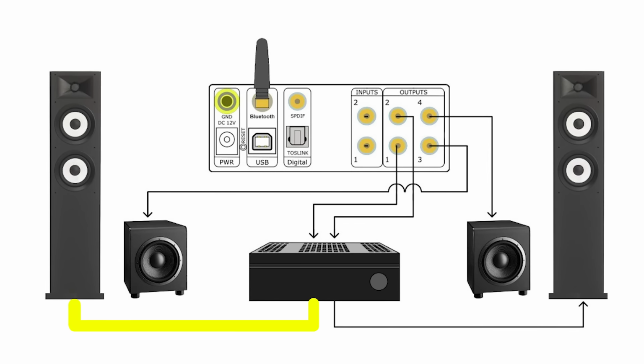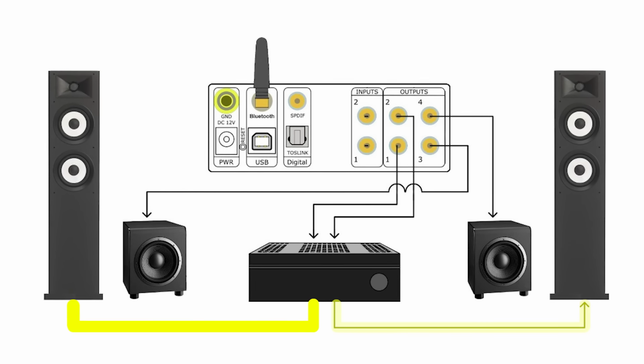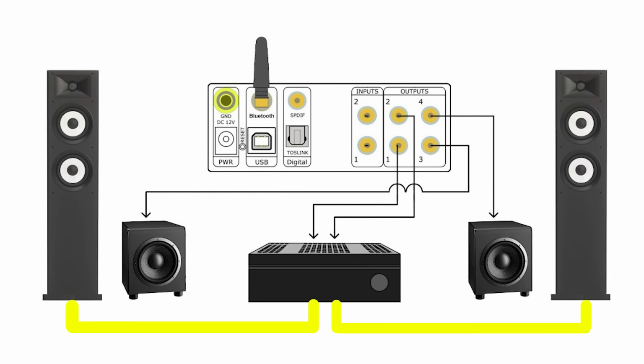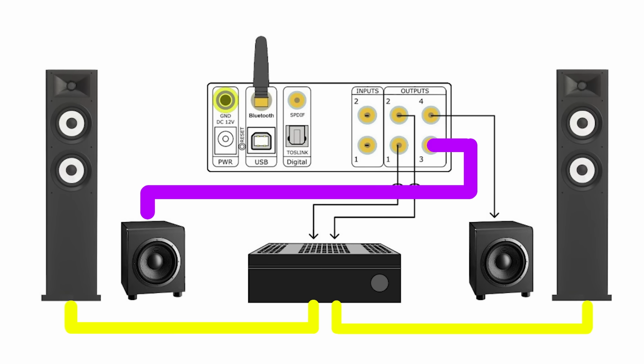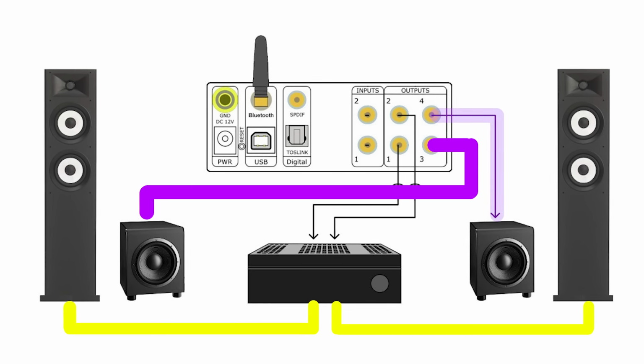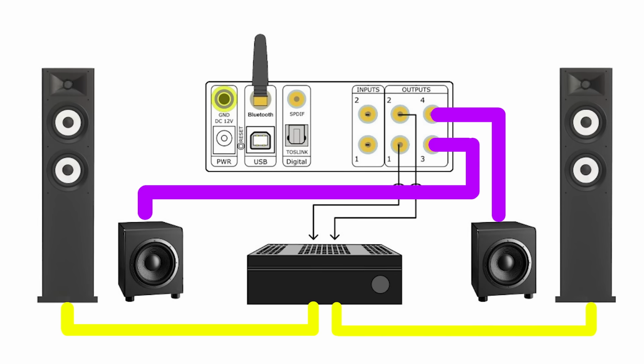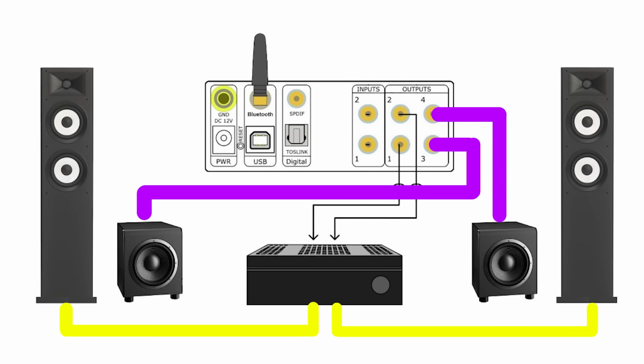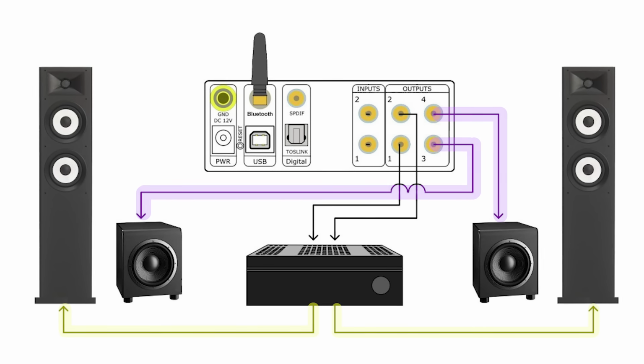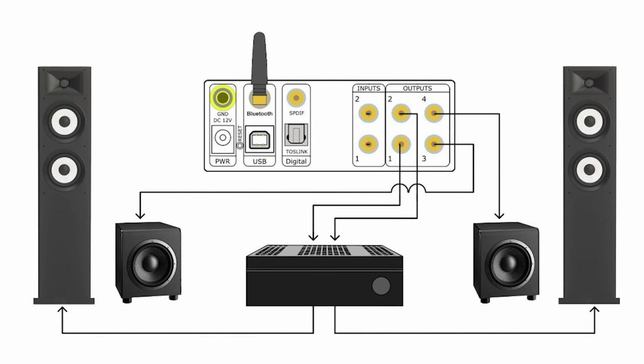Listen to each speaker and subwoofer individually, checking for similarity in tone and amplitude to confirm proper operation. If you hear significant differences between like speakers, then you should investigate further into individual driver operation. This will all be measured in greater detail later using frequency sweeps.